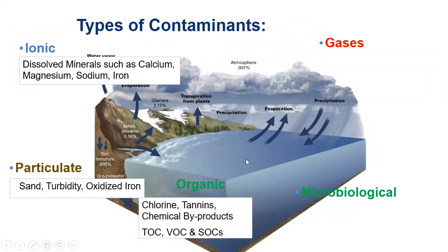Now, organics, this is the result of the byproducts of sanitation, the decay of organic material. If you've ever had a really bad glass of red wine where it's really bitter and tannic tasting or off tasting, that's from tannins. Tannins are a group of acids that are created from a breakdown of organic matter. And depending on the type of organic matter you start with and the environment in which it breaks down, we produce tannins or other organics in the water.